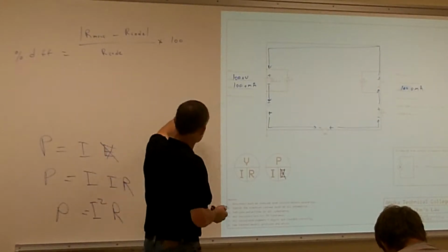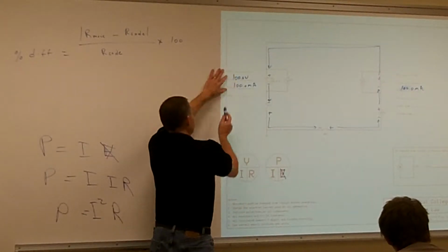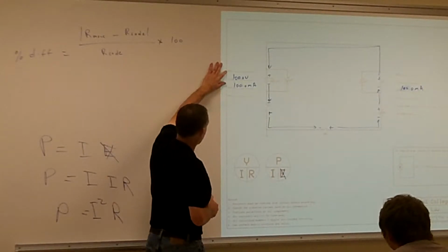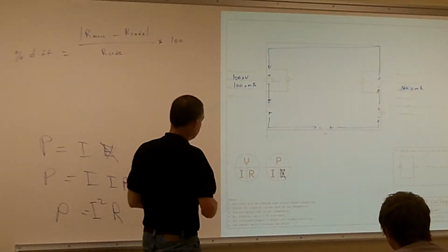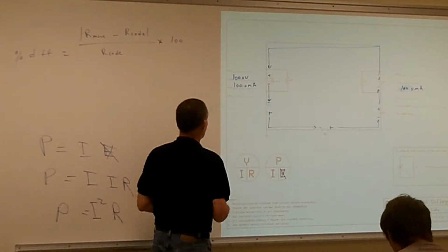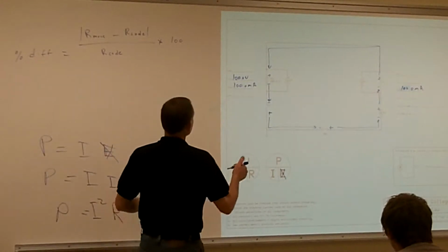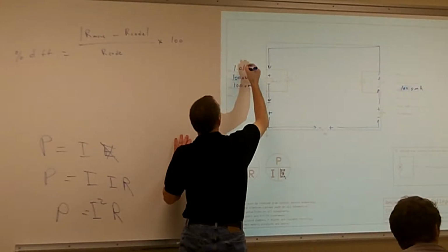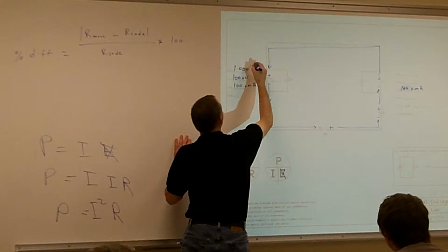Now we know two things, and once you find out two things, we can find the third and the fourth. To figure out my resistance, how do I calculate it? E divided by I. If I cover up R, I take my voltage divided by my current and I get my resistance. What's my resistance total? 1 kilo ohm. Make sure we get our four digits.